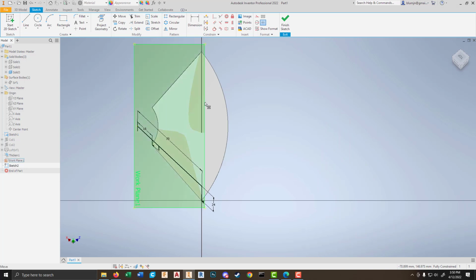So here's our sketch. Here is our object. You'll notice as I try to draw things that I don't latch on to anything. I like my green dots. I like projected lines. So we need to get this geometry onto our sketch, and we're going to do that with project geometry. There's a few different options here. In this case, because we're not cutting perfectly through, we are going to do just the regular project geometry. We will select this guy, and that'll be that.